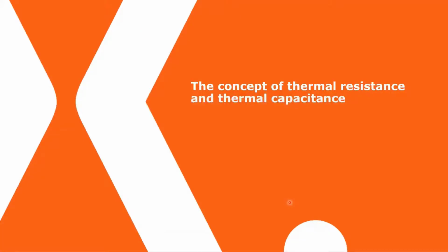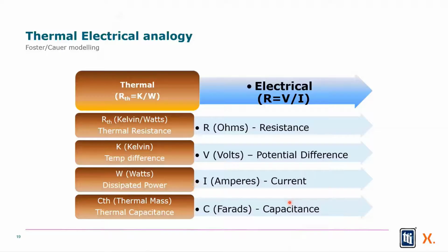RC models use resistors and capacitors to represent the thermal values, the wattage and the current, which is flowing through the motor. Basically, because it turns out from the laws of physics, they're very similar to each other. We all know about Ohm's law, V equals IR, or R equals V over I. We use that all the time for resistors, current, and voltage, very easy. Turns out there's a thermal model as well, where there is the resistance, which is K divided by watts, Kelvin divided by watts. So I can actually do a similar calculation thermally that I could do electrically.